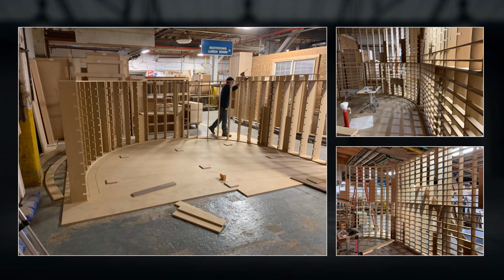So in order to install that successfully, we created the dead space behind it, painted all the drywall black, and then shimmed the panels to our 1/8 inch reveals on site. So the room you see here in the pictures is not the exact same size. We are 1 inch overall smaller, 1/2 inch behind all the panels.